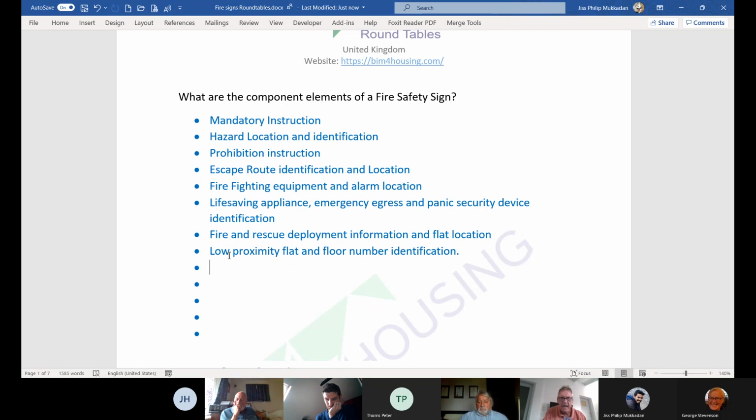Has anybody else got anything to add onto that? I would think probably not, other than I would agree, and that within emergency lighting we define that signs can be either internally or externally illuminated, and as long as, as Jim says, you can see them. Exactly. I don't think we need to get bogged down on it. And BS 5499 Part 4 and Part 10 do the same. Excellent. So I think that covers that.